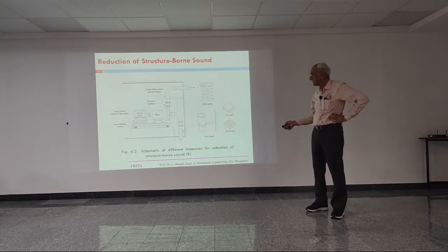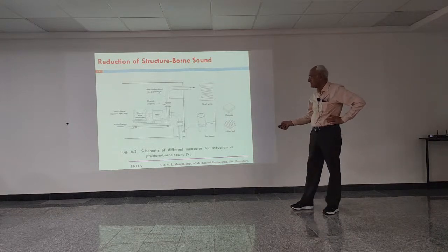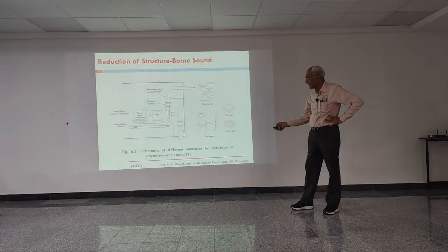Now the idea is how to make sure that this operation doesn't make too much noise. So we start from here. First thing I do is I have the support. I must make sure that my electric motor and the pump are supported in such a way that I have a single common plate supporting both.